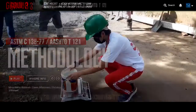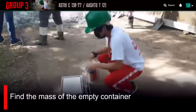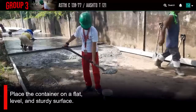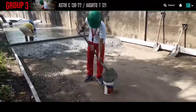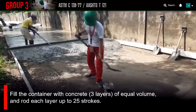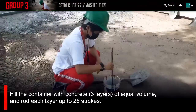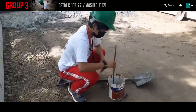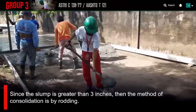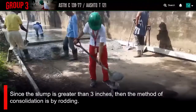To perform this test, dampen the inside of the container. Find the mass of the empty container. Place the container on a flat, level surface. Fill the container with 3 layers of concrete of equal volume and rod each layer with 25 blows. Since the slump is greater than 3 inches, the method of consolidation is by rodding.